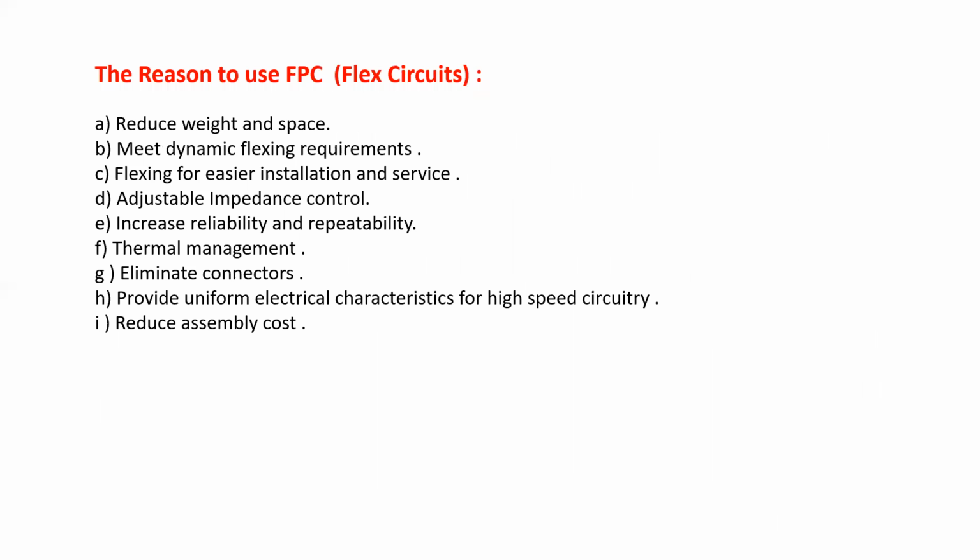Now here again, I'm going to narrate some reasons why to use flexible printed circuit boards. It reduces the weight and the space, it has more flexibility, it has adjustable impedance control, it also increases the reliability and repeatability. The thermal management is good, and it also eliminates the connectors of our normal rigid PCBs. It also provides uniform electrical characteristics for high-speed circuitry. It also reduces the assembly cost.